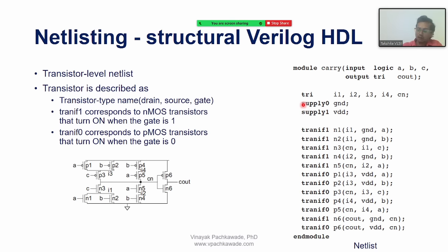So I have one question. Is this netlist technology independent? Yes, this Verilog HDL structural Verilog netlist is technology independent. Good question. But when we go for implementation, the tool knows which technology it has to implement. But there is another netlist called SPICE. That is technology dependent, because there we will see how that netlist is defined.